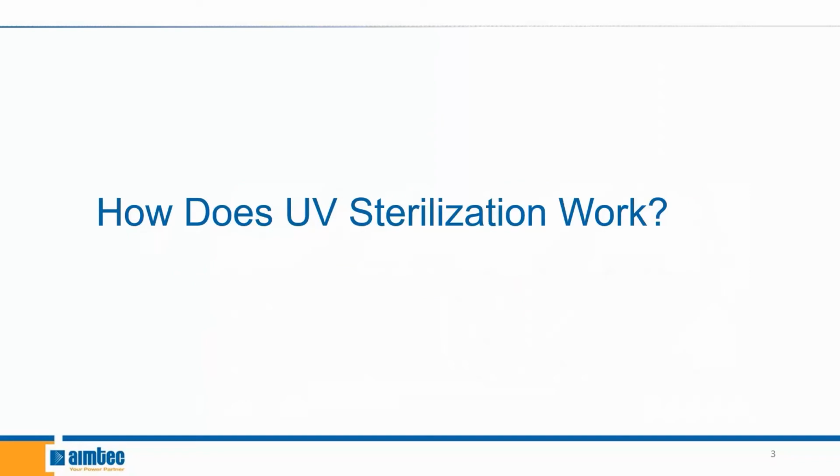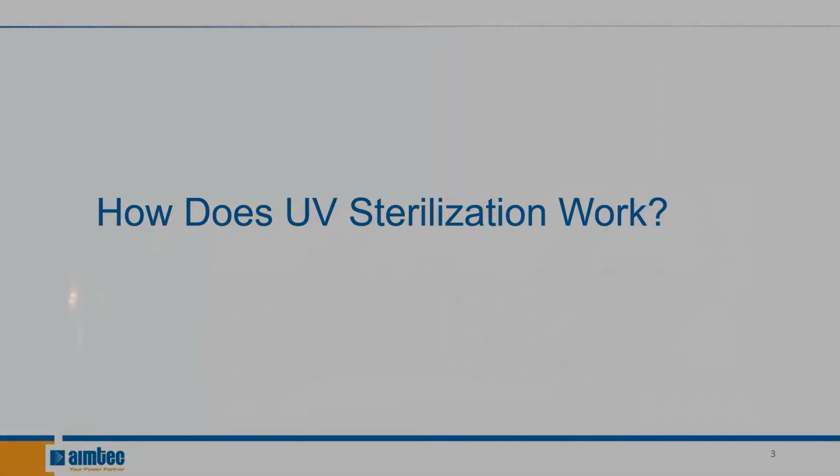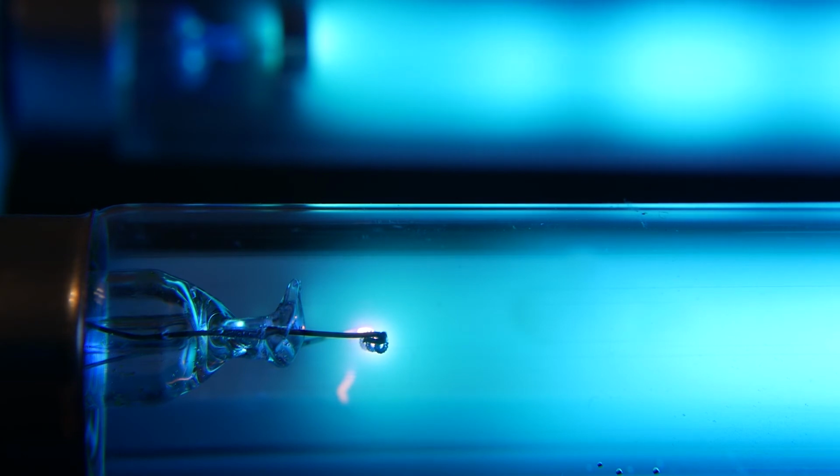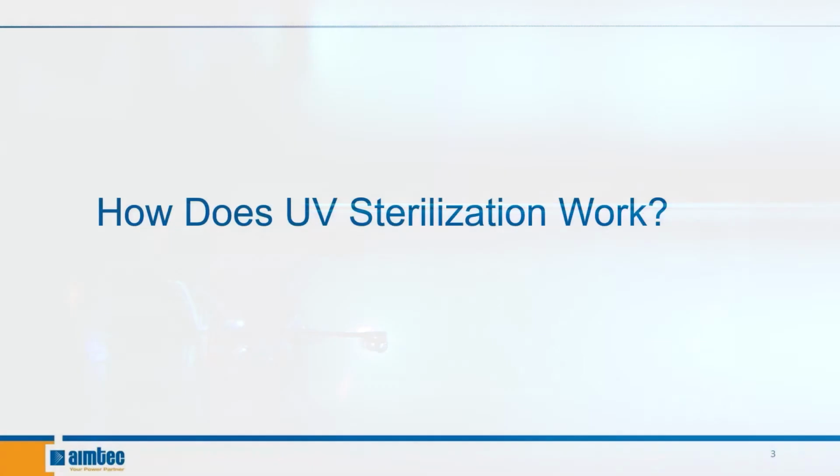Unlike chemical approaches to water disinfection, UV light provides rapid and effective inactivation of microorganisms through a physical process. When bacteria, viruses, and protozoa are exposed to the germicidal wavelengths of this UV light, they are rendered incapable of reproducing and infecting. UV light has demonstrated efficacy against pathogen organisms, including those responsible for cholera, polio, and typhoid. In addition, UV light, either alone or in conjunction with hydrogen peroxide, can destroy chemical contaminants such as pesticides, industrial solvents, and pharmaceuticals through a process called UV oxidation.